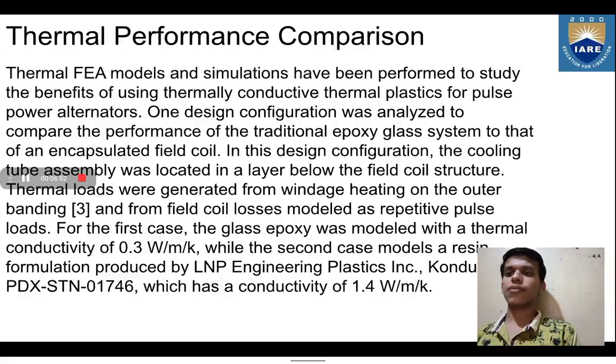One design configuration was analyzed to compare the performance of the traditional epoxy glass system to that of an encapsulated field coil. In this design configuration, the cooling tube assembly was located in a layer below the field coil structure. Thermal loads were generated from the windage heating on the outer banding and from field coil losses modeled as repetitive pulse loads.